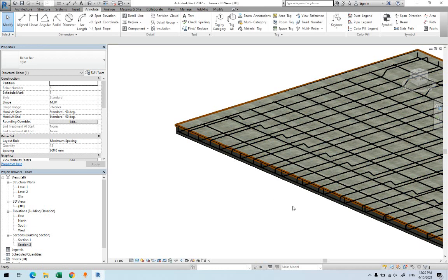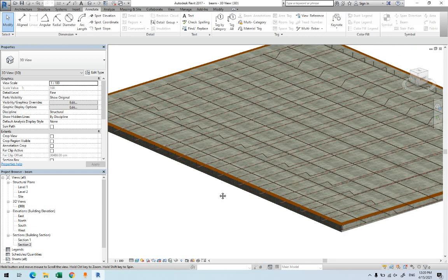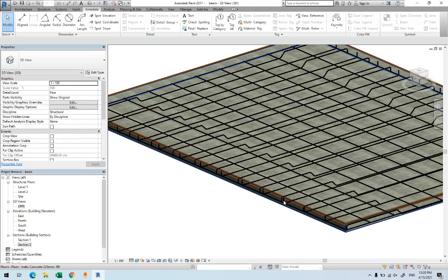Remember, any extra additional reinforcement that you want to add, you can go for sketch. For example, sometimes in some codes, the corners have reinforcement like this. Now you can provide those with what? With the sketching. You can go and sketch this one. This is according to the negative moment, where these corners will be cracked. Some codes provide this reinforcement. Or maybe you have a gap and the reinforcement is not going to be regular, so you have to go with the sketching. Remember, sketching is something more professional. You will be able to do whatever reinforcement shape that you want to model.